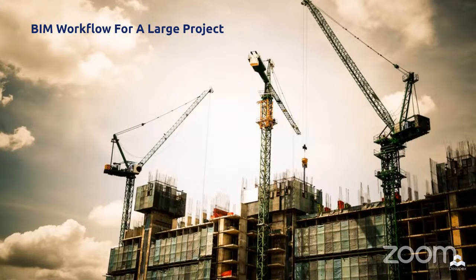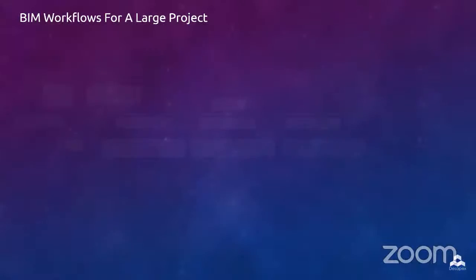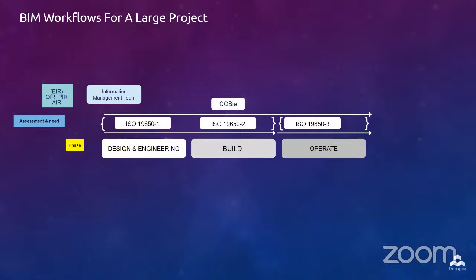As with any building or infrastructure, it begins with the owner, or the so-called appointing party as per the terminology of ISO 19650, who has the notion of building its new place of operations. In the initial programming stage, or assessment and need, as per ISO 19650, the BIM framework requires the owners to document the organizational information requirements, project information requirements, and asset information requirements, which are acronyms for OIR, PIR, and AIR.